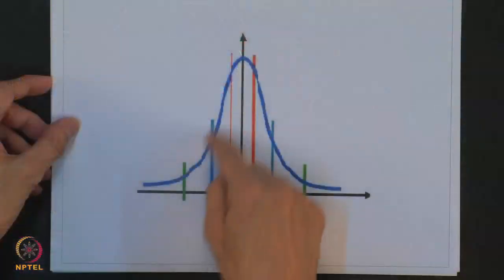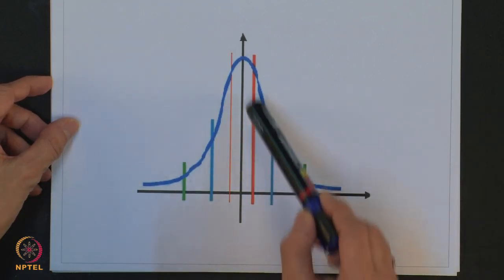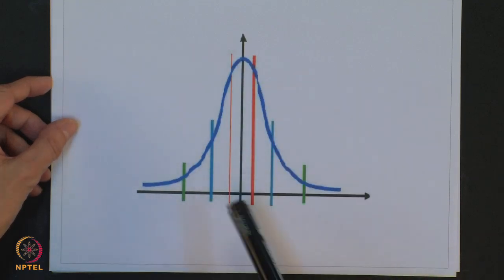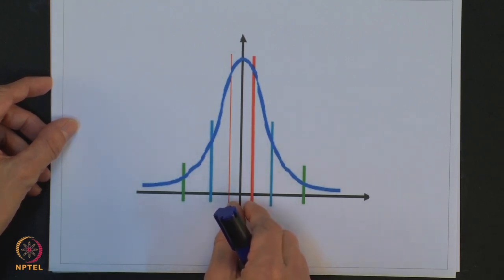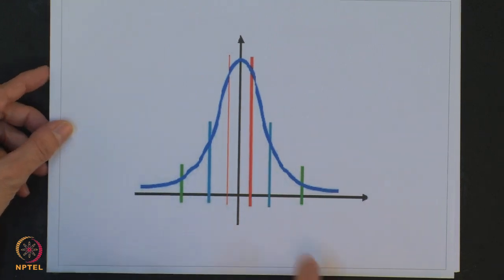Now, we will study this, and the problem is as shown in this slide. Suppose, for example, I have a PDF of this form. Since the probability mass is high near the origin, I start allotting my quantization intervals such that near the origin the step size is small compared to as we move away from the origin, correct? Fine.